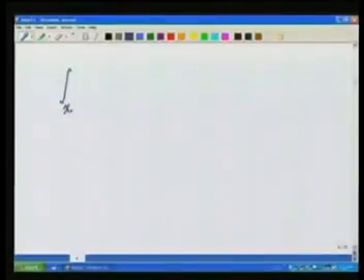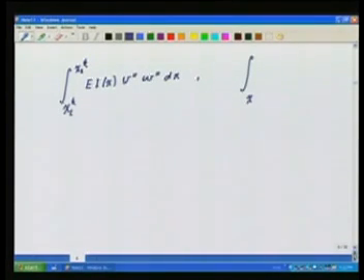Okay. So at the element level, which are the integrals that are active? It is the integral from x1 of k to x2 of k of EI(x) V double prime W double prime dx, and the integral from x1 of k to x2 of k of qw dx. Q is my transverse load that I have applied, so I am using F or Q accordingly here. I am mixing the two, but it should be Q because according to the convention for beams, transverse load is generally given the name Q.